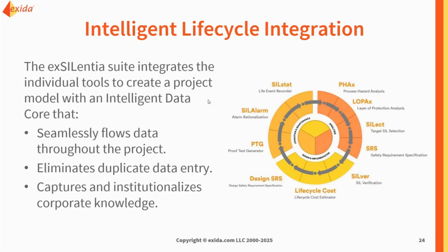So all your field performance information would be in there, because let's not forget, we're supposed to be doing FSA 4s according to 61511, which is comparing the performance we're measuring with the original design criteria to see whether our performance is matching or not.